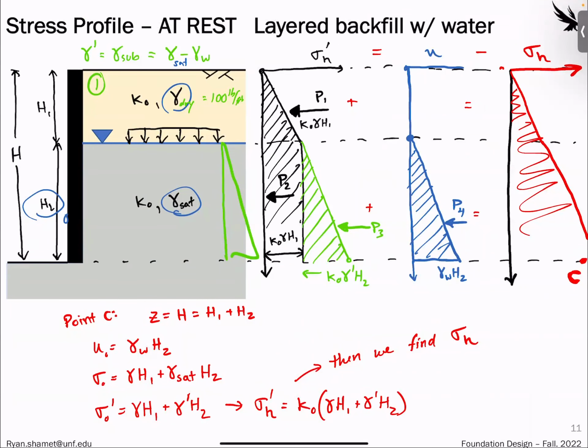We've seen these plots before, but it's always been vertical. So when we're talking about vertical stress and plotting the vertical stress, then we can usually just combine these two. We just use gamma saturated. But we can't do that when we're doing horizontal earth pressures because of this K value. The K value is acting on soil only. The K value doesn't act on water. So that's why we have to separate the two.